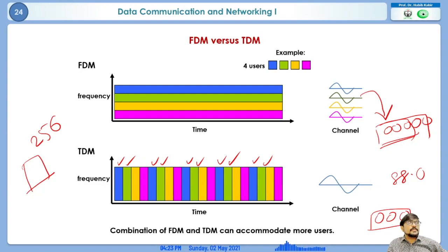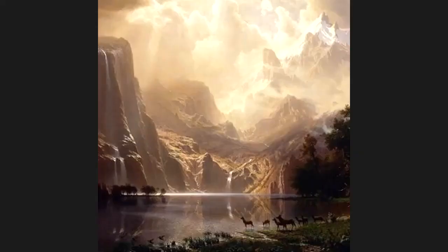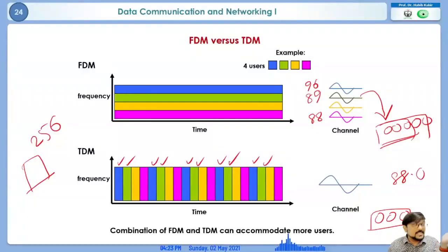Yes, sir. We learned about the RLC circuit. If I tune the capacitor in a perfect way, it will create resonance. It acts as a kind of filter: it will pass the perfect frequency, and the other frequencies will be blocked. So by changing the capacitor, I can change the filter configuration and selectively listen to certain frequencies and block the others.